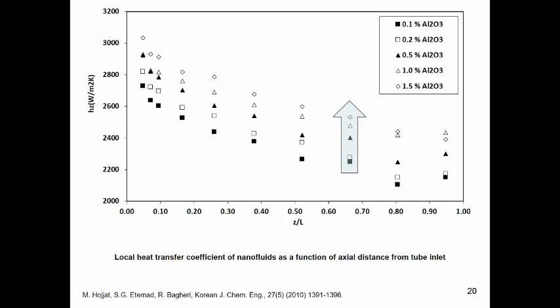These results show that the entrance region for nanofluid is longer than that of the base fluid and increases with increasing nanoparticle concentration. This is due to decreasing thermal boundary layer thickness of nanofluid relative to that of the base fluid. Similar trends were observed for other nanofluids and other Peclet numbers.